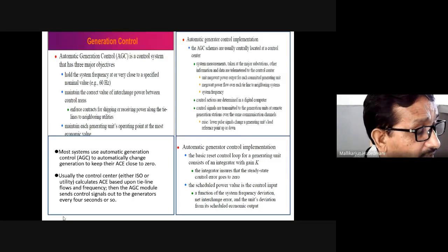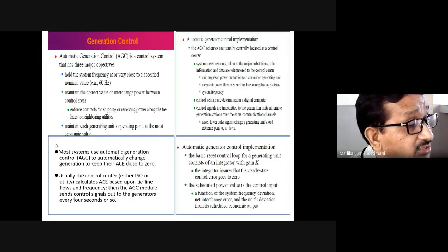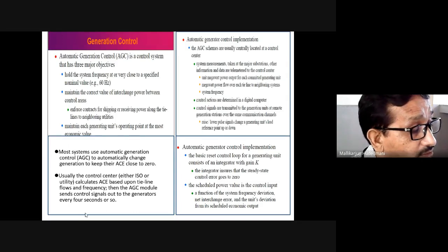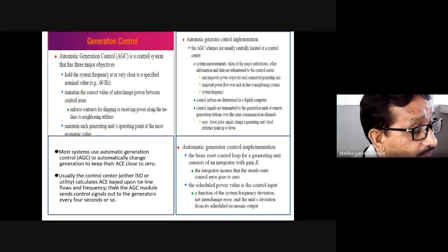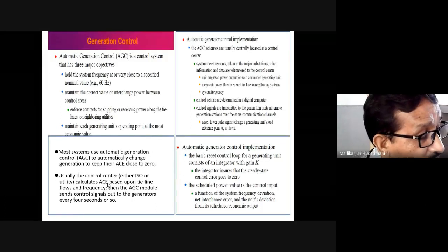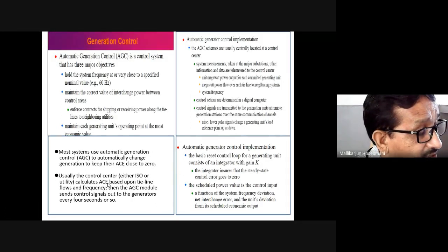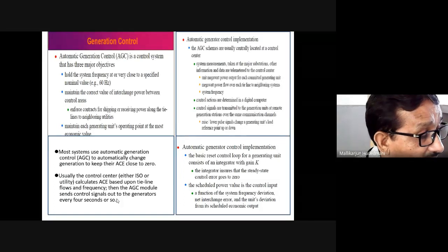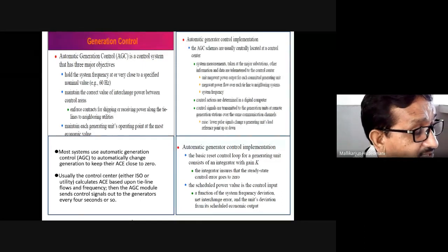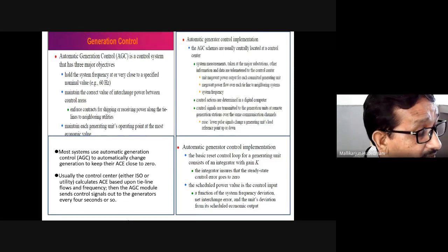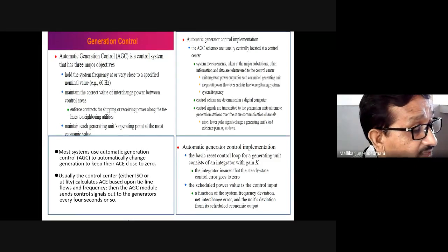Power flow is occurring. Then the automatic generation controller concerned with area A checks whether the area control error of that station is 0. When it is 0, what megawatt is it exchanging? All that calculation is done. Then, to work towards maintaining the error of that station at 0, it will start accelerating the generation set point.